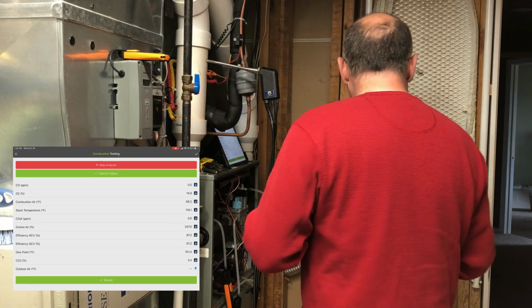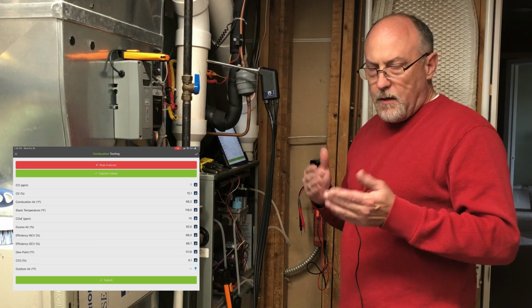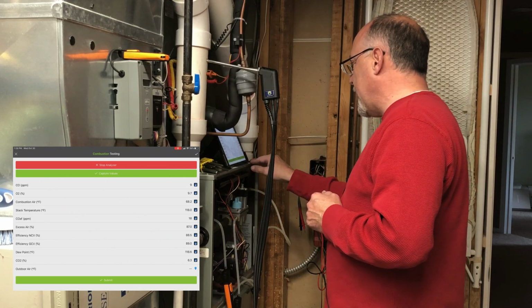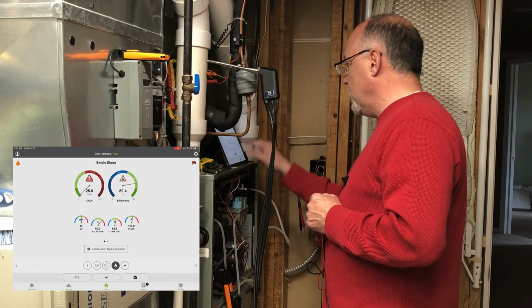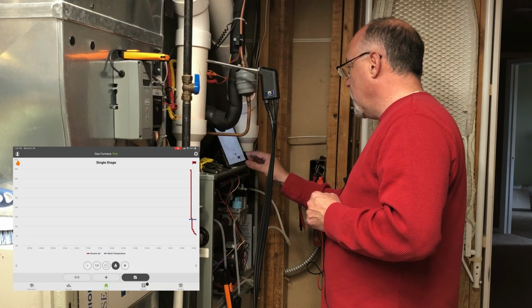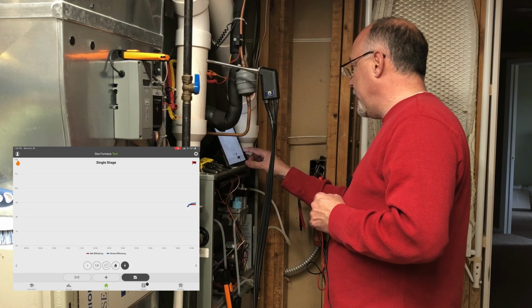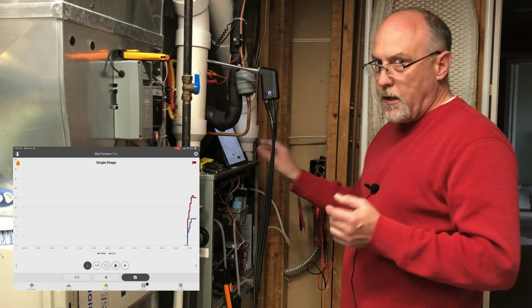So it's going to take a few seconds for the analyzer to stabilize out. So we're going to be looking at our temperatures, our pressures, that kind of stuff. And right now our CO is about 9 parts per million. And again, we can go back and we can look at our trends. This is really a good place to start looking here. CO and CO air free are probably where I have to look on there.